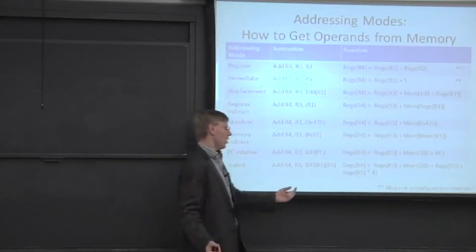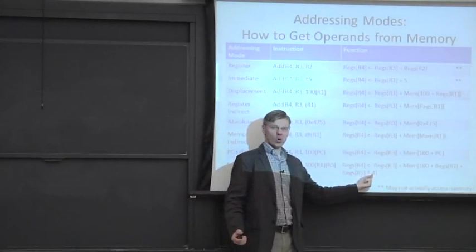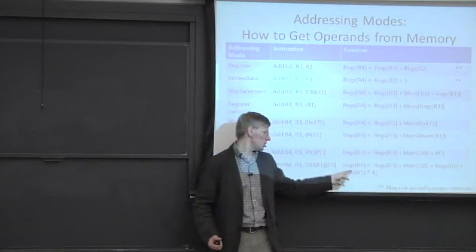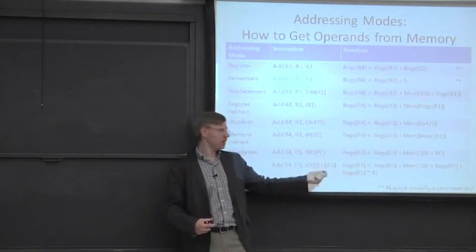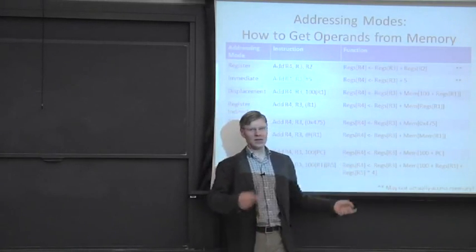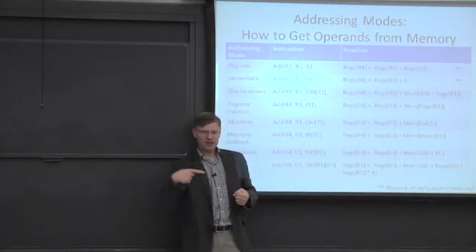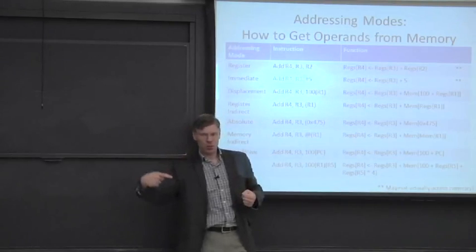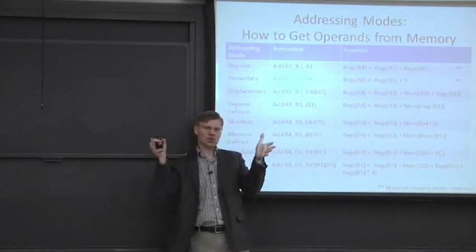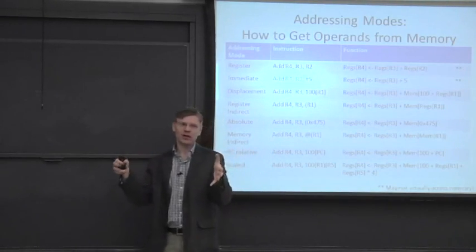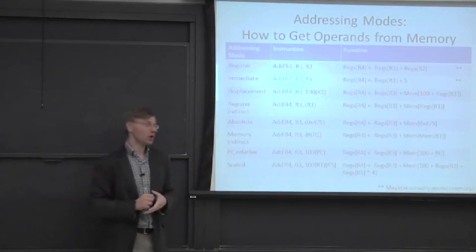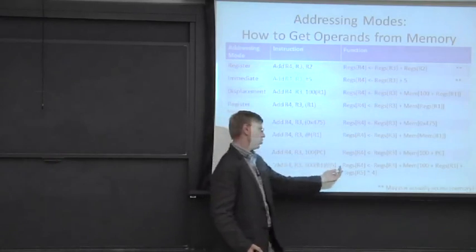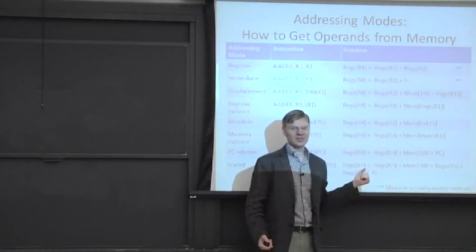If you have an array of 4-byte words, you can just keep ticking up this counter. So you start off 0, 1, 2, 3, and as this ticks up, instead of going up by a byte, you'll go up by 4 bytes at a time. And if the data you're trying to load is 4 bytes long, you'll be able to pick up the exact elements in the array you want, versus having to do this multiplication someplace else.